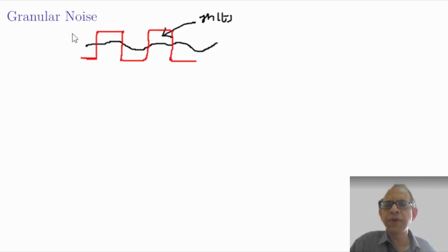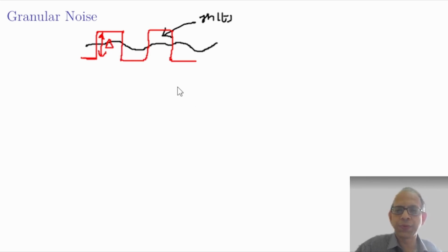So what we observe here is that all the signal variations are within the step size delta. What happens is that we get alternate positive and negative pulses, and therefore when it is passed through a low pass filter for reconstruction at the receiver, we get a straight line, all variations are lost, and therefore the information is lost.